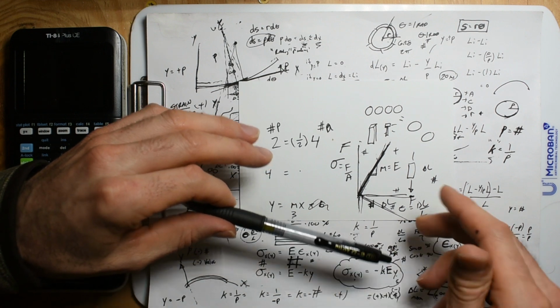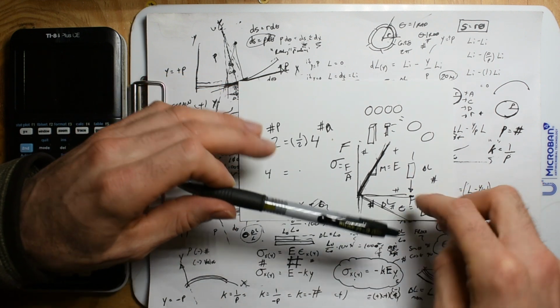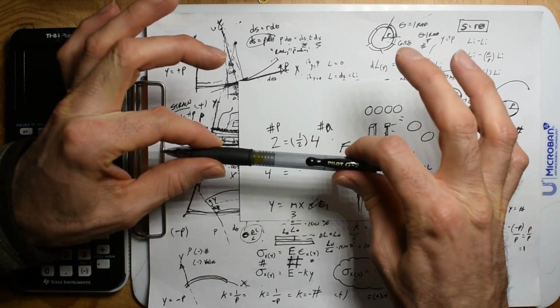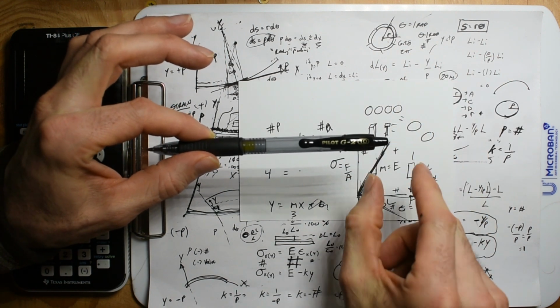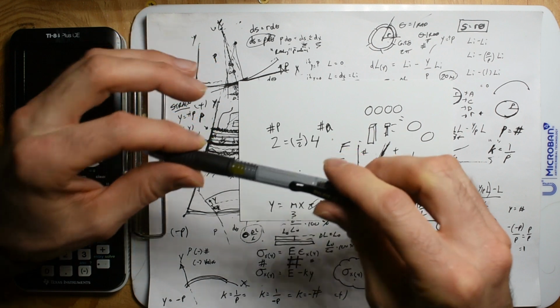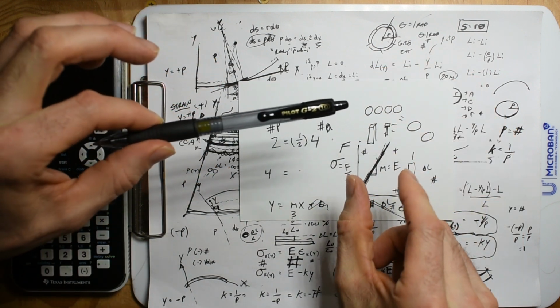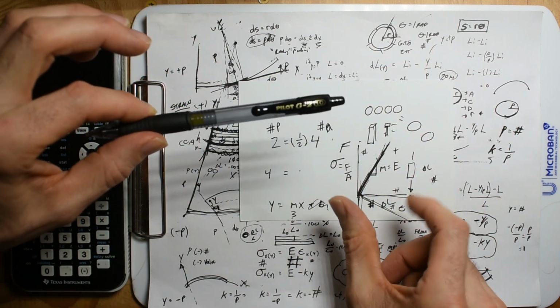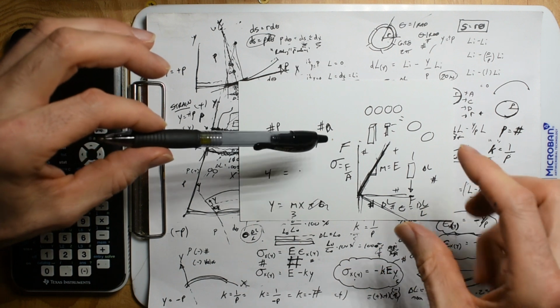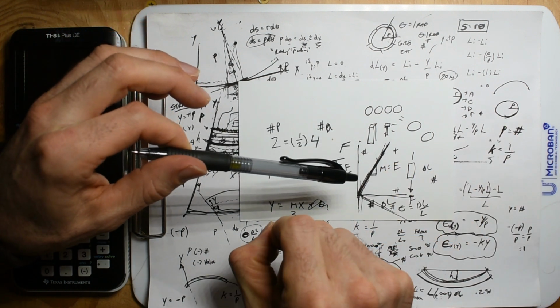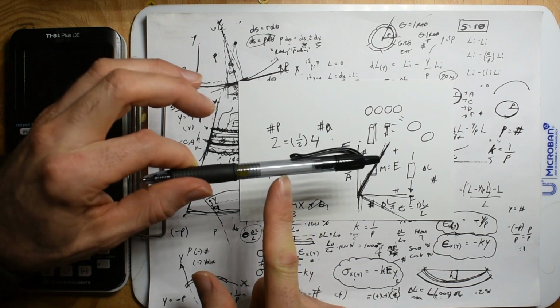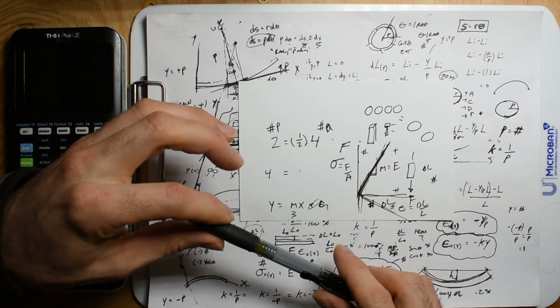And it doesn't even matter that it's divided by the initial length. Again, 5 pounds of force on this pen, molecularly it changed length that much, let's say. And then if I put 10 pounds, that change in length doubled. It's only the fact that we take that change in length and divide it by a length that now we actually have a material property for that material, plastic, steel.